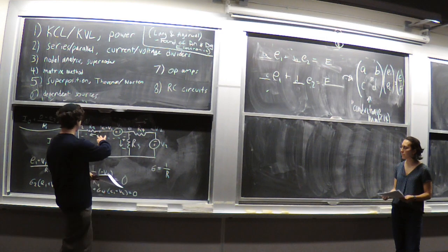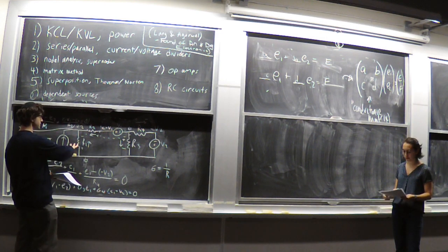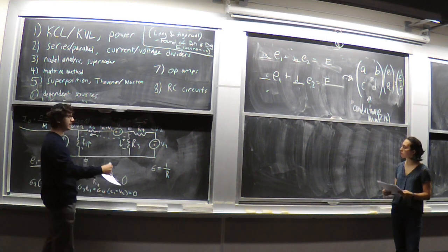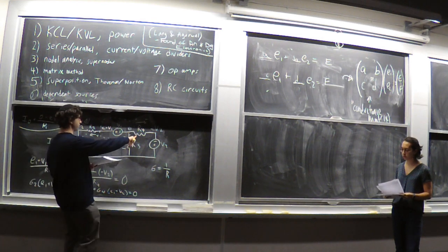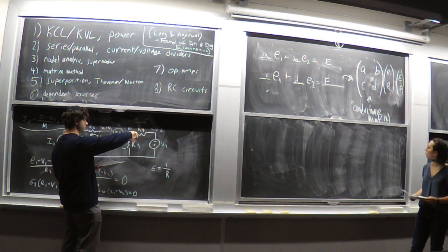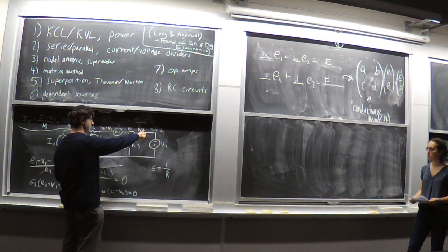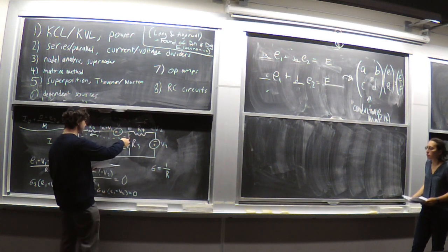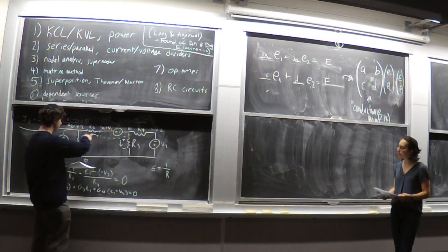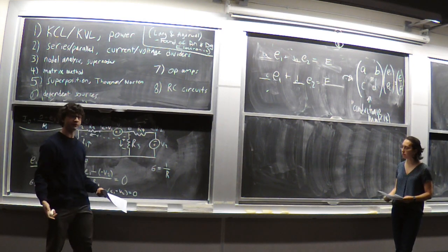And so now all of a sudden we just have this current source and then this whole network of resistors. And as we were talking about before, R3 and R4 are going to be in parallel once this is just a wire because they share this node and they also share this node. So these guys will combine and then they'll be in series with this and parallel with this. The circuit's going to simplify a lot.